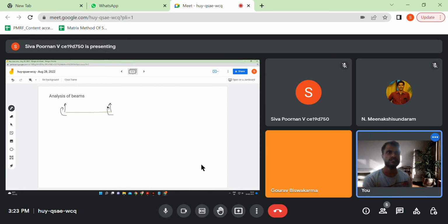So you have four unknowns here. These 4 unknowns are the displacement degrees of freedom u1, theta 1, u2 and theta 2. Now we know that these 4 things should be related to the corresponding shear forces and moments applied at those points using the stiffness matrix. From our previous knowledge, we know that force and displacements are always related linearly.